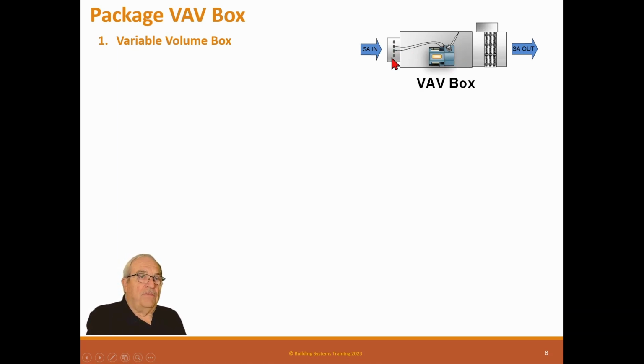There's a velocity sensor in the inlet cone of this box, and he's calibrated it to say that at the maximum flow of this box, this set point, the velocity pressure is this. So if the pressure changes upstream, this damper will modulate slightly to make up for that pressure, but it will always maintain the CFM the room sensor wants to cool the room.